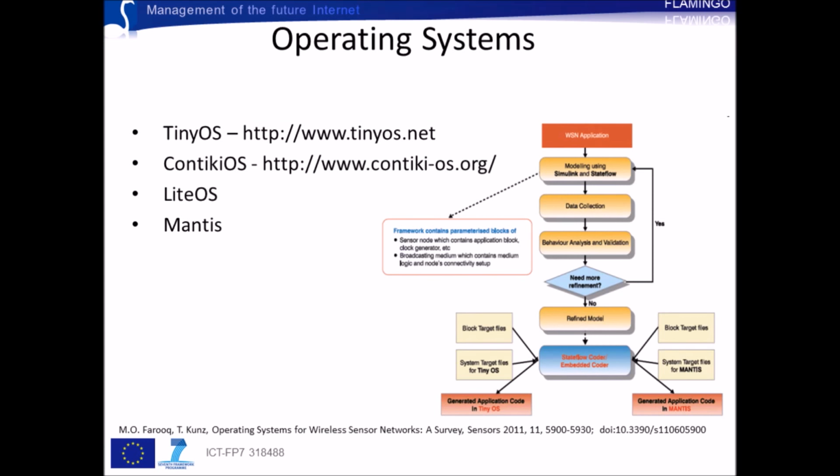Different hardware also requires different operating systems. In general, they have a modular structure, but may include constraints for hardware, programming language, and support of resources. For example, TinyOS was especially developed for hardware from Crossbow, like Iris or TelosB motes, listed in the slide before.